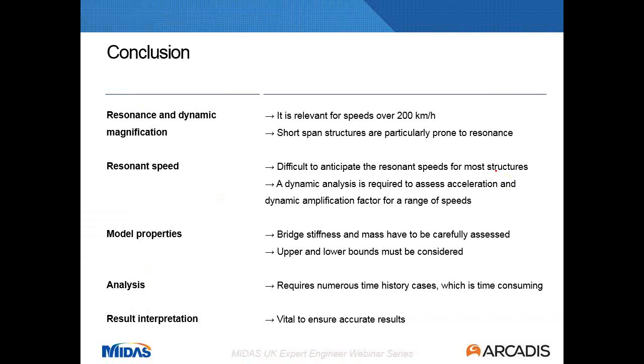Last thing, result interpretation is very important. You carefully check your results, make sure that they make sense, and that you're capturing these resonance speeds and the peak values, so you're designing your bridge to the most onerous effects.